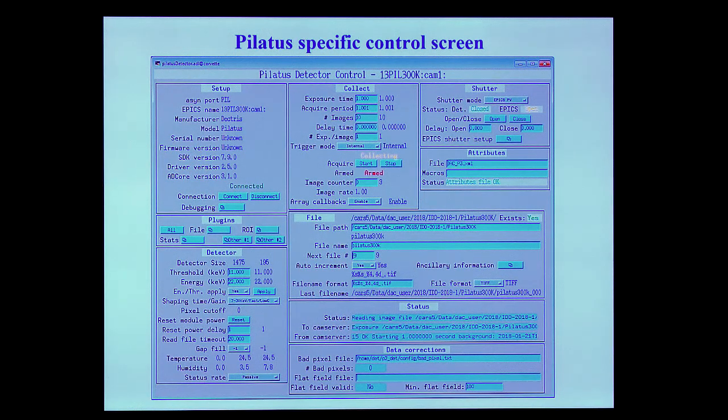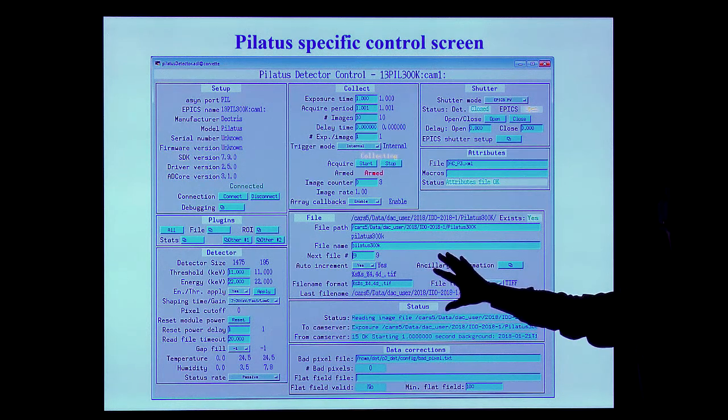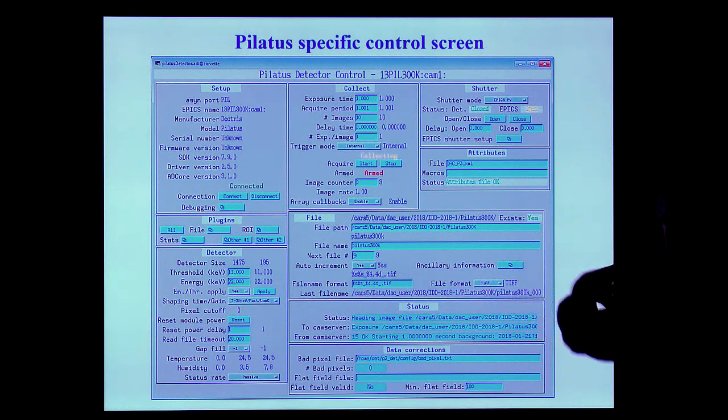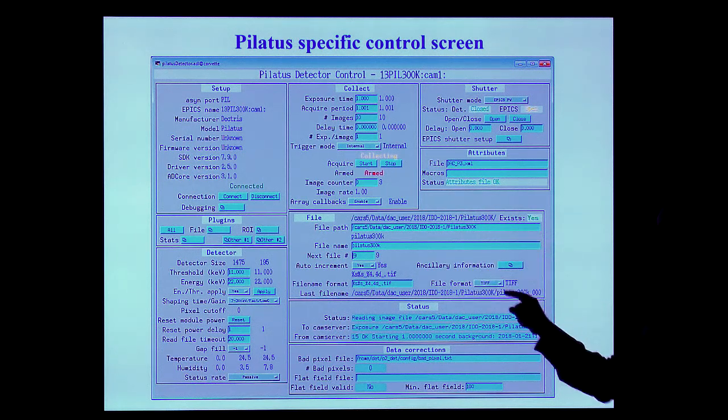The flipping of the images would have to be done in a plugin called a transform plugin. If the vendor supported flipping, which Point Grey does, then you can do it in the vendor library. But the Pilatus CAM server doesn't support flipping images, so you would have to put a transform record into the processing pipeline, either before you see the images, if you only need to flip them for the operator, or if you want them flipped in the final data file that you're writing.